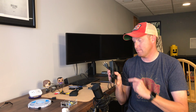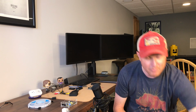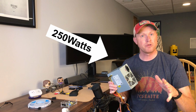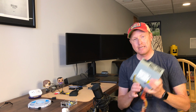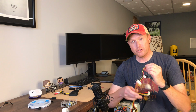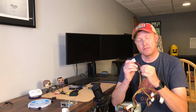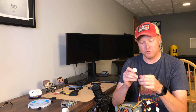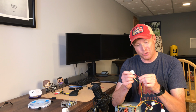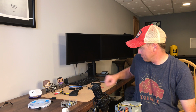Now you can buy a big power brick like this, and I'll leave a link down below to one that might work for you. But for me, I'm going to be using a computer power supply. I have an old computer around my house that is now obsolete. I ripped out the power supply and I'm going to use this to power the LEDs. If you look at the power supply and all these little plugs that plug into hard drives, this red wire right here is 5 volts and this black wire is ground. So I'm going to be stealing these 2 wires off this power supply to control the LED light strip.